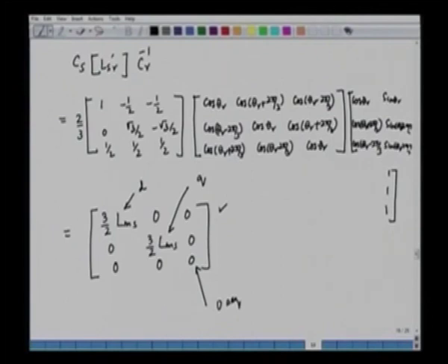So, this is obviously coming because of the transformation, and in the DQ model we have seen that the inductances are not a function of the rotor position, that is, independent of theta r. So, with this background we can write down the equation of the induction machine in a stationary reference frame or in the stator reference frame.